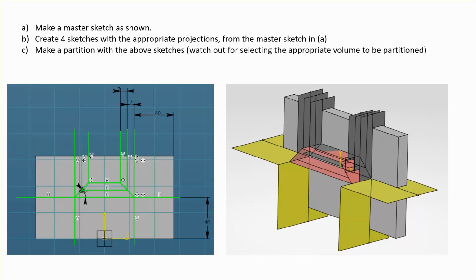Okay, so here's the strategy. I do draw that sketch on that front face. However, when it comes to making partitions, I select 4 sets of surfaces. One of them is extruding this stuff here on the top left corner without these slanted lines. And then you get this extrude, that's dark gray. And then 2 extrudes of these trapezoids, so we get 2 surfaces over here. And finally, an extrude of this bottom left and right corners, which is you're going to get the edge.